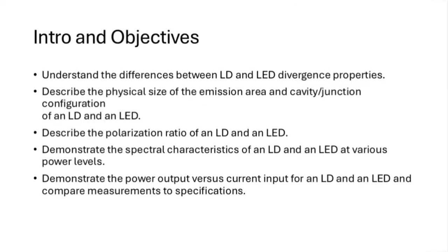So essentially this entire lab is about comparing and contrasting the laser diode with the light emitting diode. We're first going to start off by measuring things like cavity length and then work our way more towards the optical properties such as emission spectra, polarization, beam divergence, and then seeing how they both function under power.